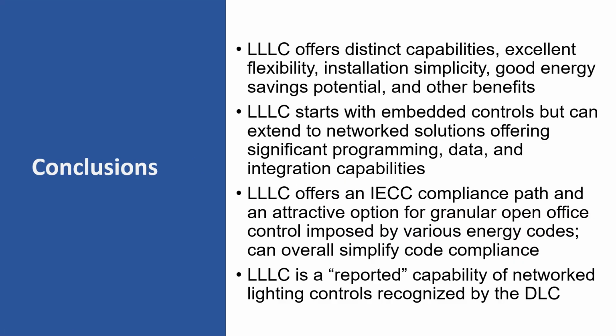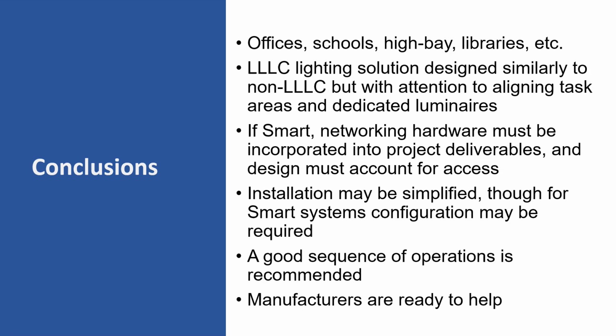Luminaire-level lighting control offers distinct capabilities, excellent flexibility, installation simplicity, good energy savings potential, simplified energy code compliance, access to rebates, and other benefits. It starts with embedded controls but can extend to network solutions for additional capabilities. Luminaire-level lighting controls are highly suited for offices, schools, and a range of other applications. These luminaires are designed and installed similarly to non-luminaire level lighting control luminaires, but with special attention to aligning luminaires in task areas, as well as configuration of any special hardware that may be needed.